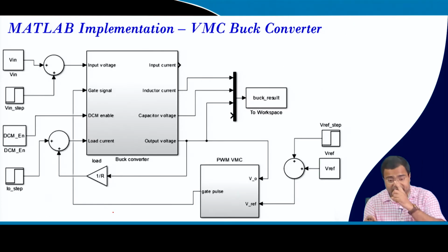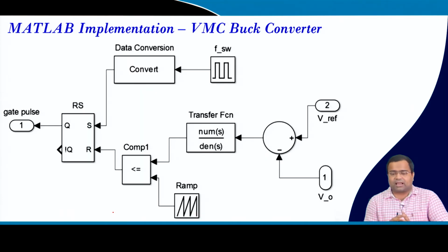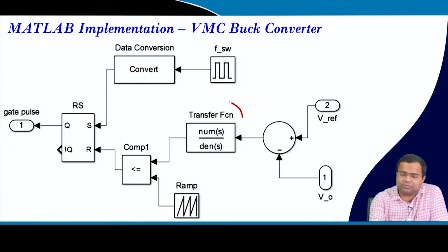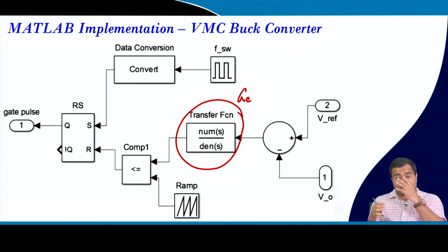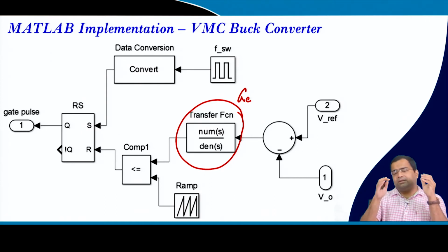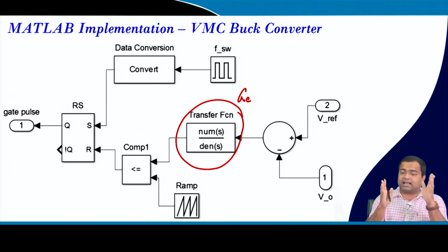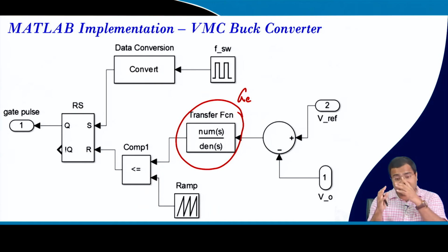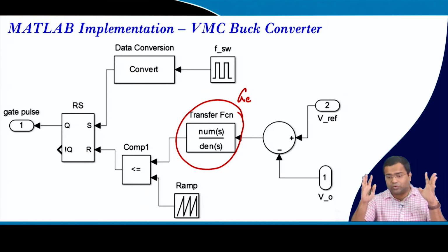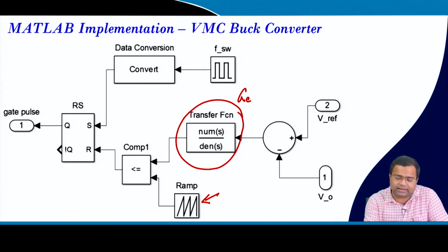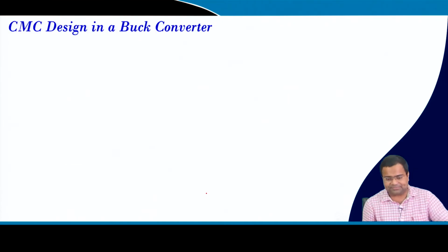And we have already discussed multiple times the block diagram, the MATLAB diagram of the voltage mode control, which we are not going to discuss again. In this voltage mode control we are setting the compensator. This is our GC controller, the type 3 compensator, that we set from our MATLAB code, and we know how to design it. It will ask for the phase margin as well as the gain crossover frequency, and then for the buck converter you have two flexible choices, and you need to provide the RAMP in order to find the controller gain.